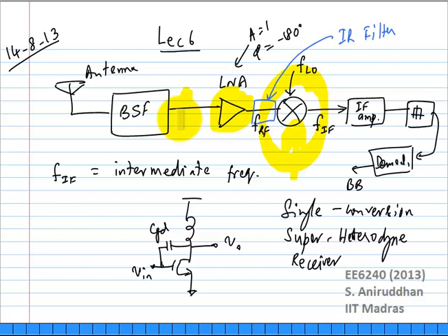Matching could be a problem. Okay. What kinds of ADCs do you know? Flash ADCs. Then what else? Delta Sigma, SAR, pipeline. Each of these has different trade-offs depending on the resolution you want and the frequency at which you can operate it.